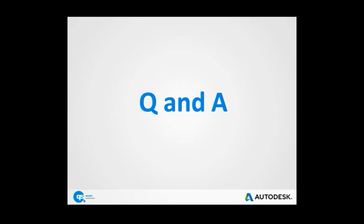Right, okay. And just as well, in terms of the licensing, because I mentioned before in the presentation, everyone, that Nastran in CAD is a network license only, so it can be shared between multiple seats. But do you know at what point it borrows the license from the server? Because you've got the Nastran tab in there. When you click on that tab and you bring up the environment, it then takes that license from the server. I typically would keep it until Inventor's shut down. Right, so you borrow it and it takes a license from Nastran, and then when you close Inventor, it then sends it back to the server. Right, okay. That's useful to know.